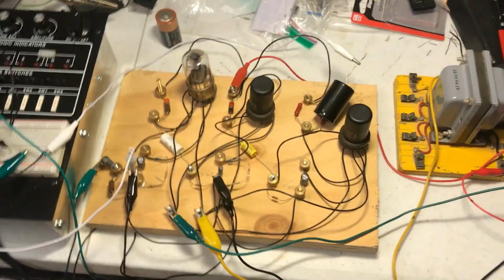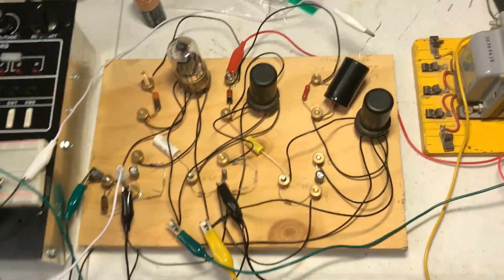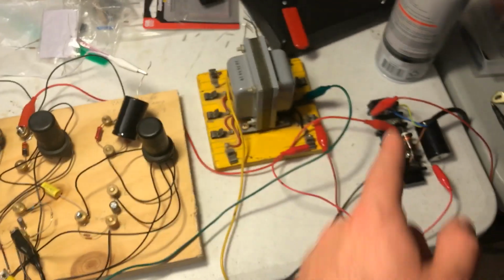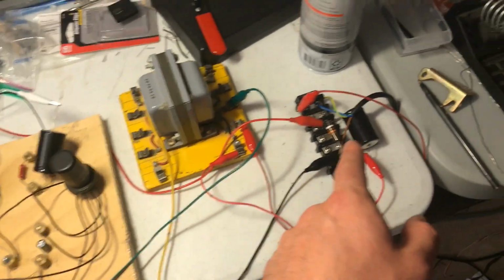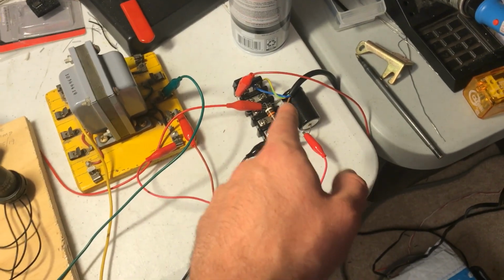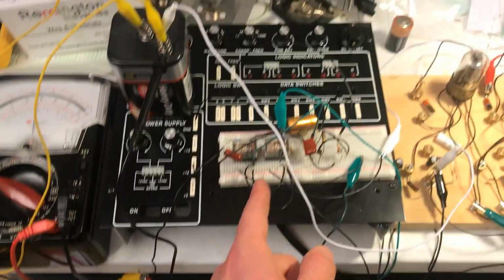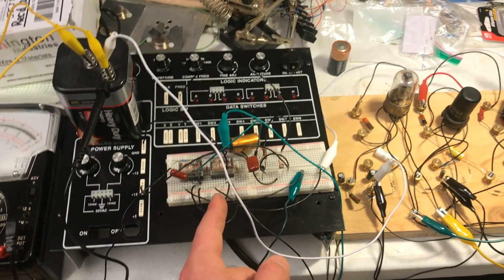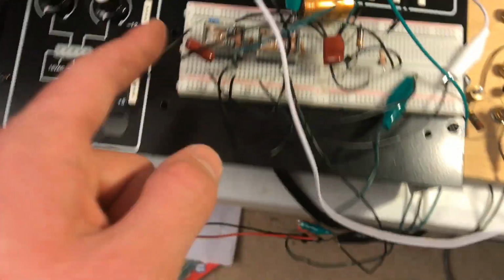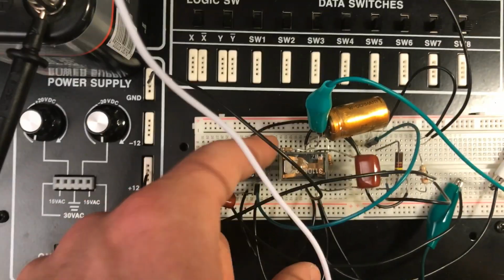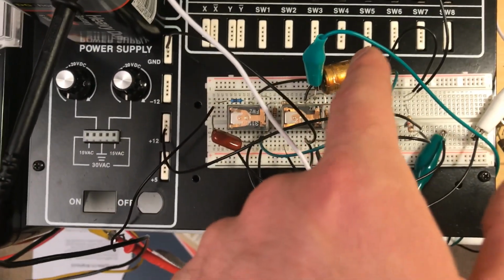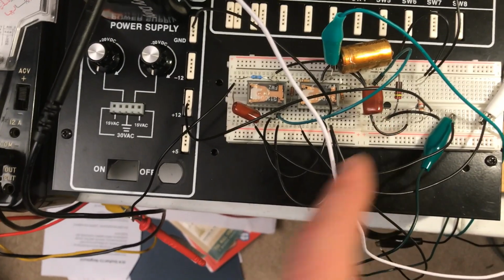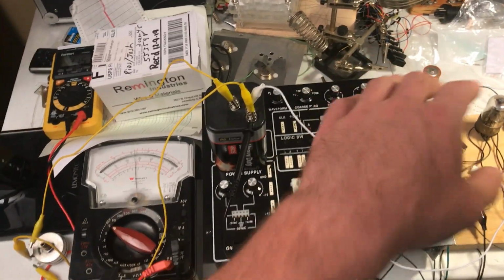As you can see, I use 1930s brass screw construction. That provides the filament. Literally the wall power comes directly from the wall after a half-wave rectifier. And these are the relays that convert direct into alternating, amplify the alternating, and then convert it back to direct. Your feedback resistors are those two. The filter cap there is what's on the rectifier side, and these are just for stability. This function generator here is what's timing the relay.